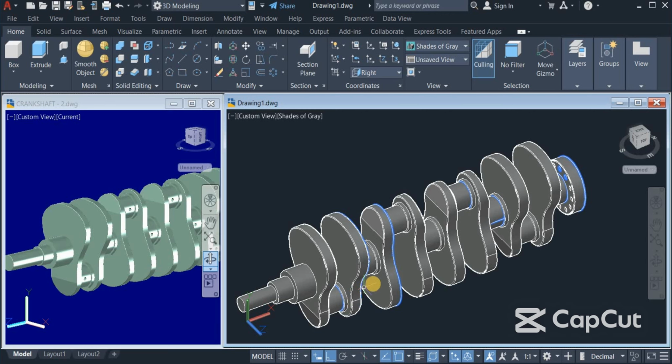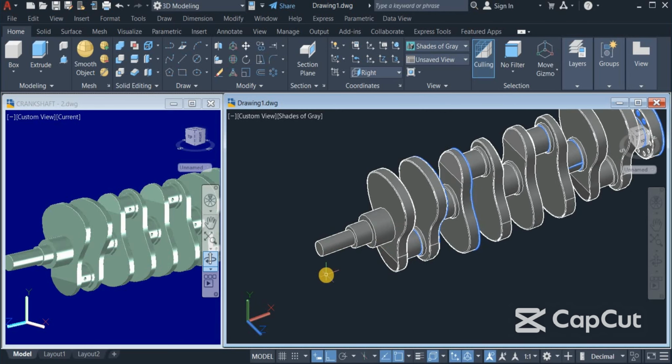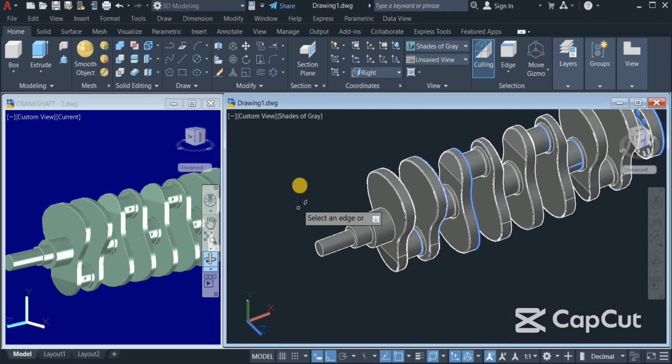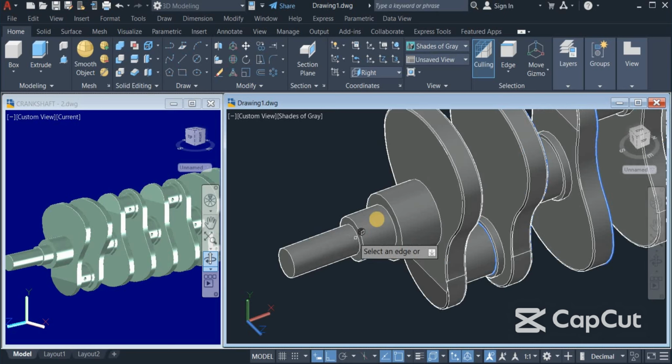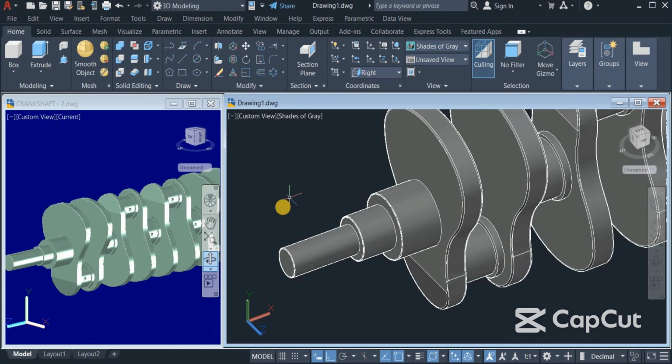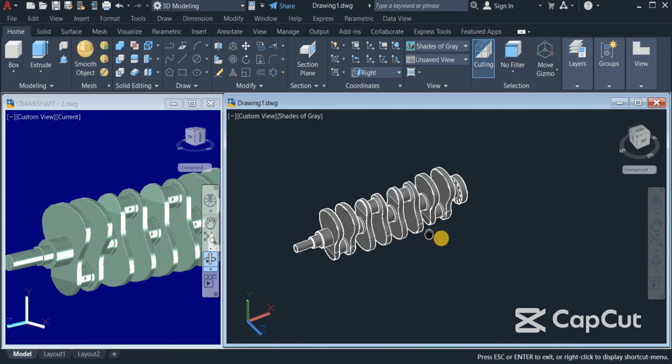Okay, so I also have to apply fillet edge on these ones. I made the radius 1 this time. So click on F, type fillet edge and choose a radius of 1. Enter. Apply radius of 1 on this, on this, and enter. Okay.